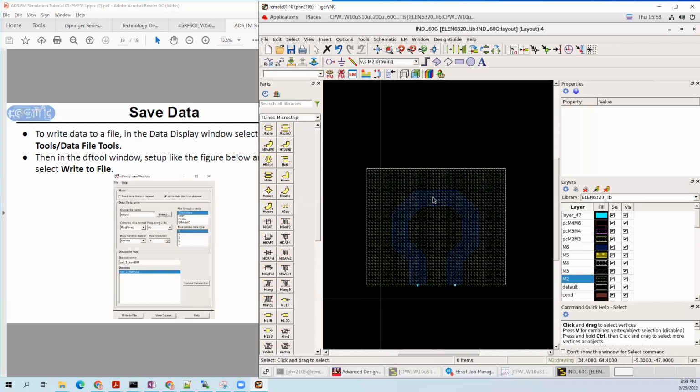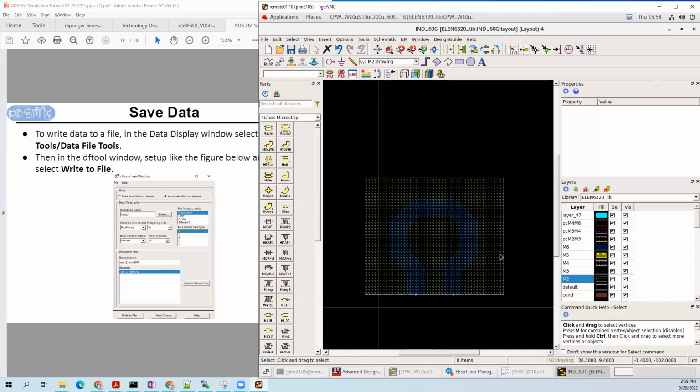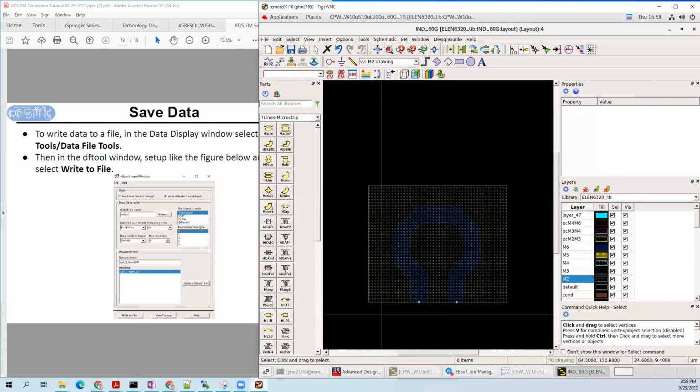That's a different trick. Because we have a ground plane underneath the inductors. In the class, the professor drew a parasitic model of the inductor that has an inductor, some resistors, and some capacitors. This model, right? So this capacitor, C shunt, comes from the metal M6 to M2.